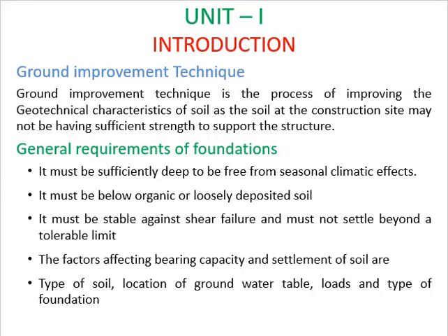Hence, there is a need for ground improvement to enable cost-effective foundations and to reduce the detrimental effects of contaminated soil. Not only the contaminated soil, other problematic soils like expansive soils, collapsible soils, landfill soils also need ground improvement techniques before planning a structure above them. Now let us discuss the need of ground improvement techniques in detail based on the soil conditions at the site which demands the ground improvement.